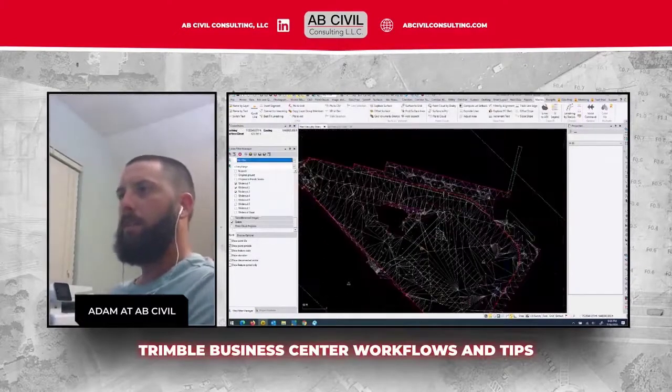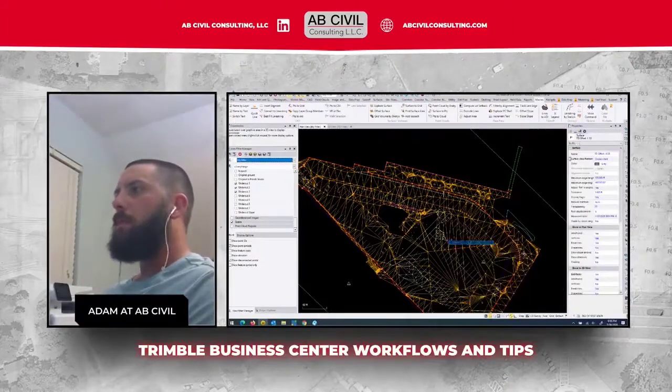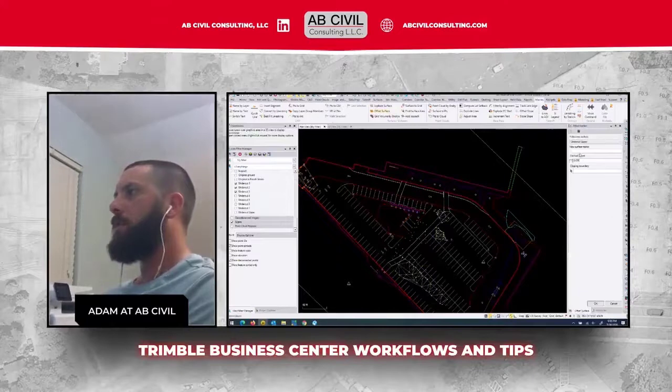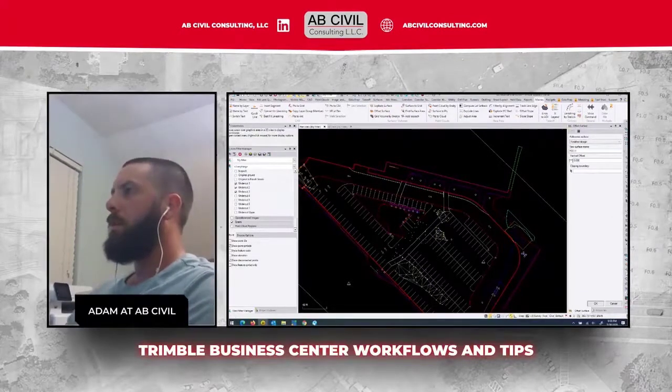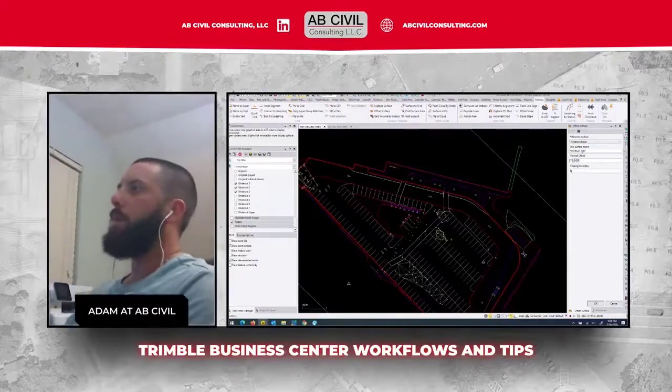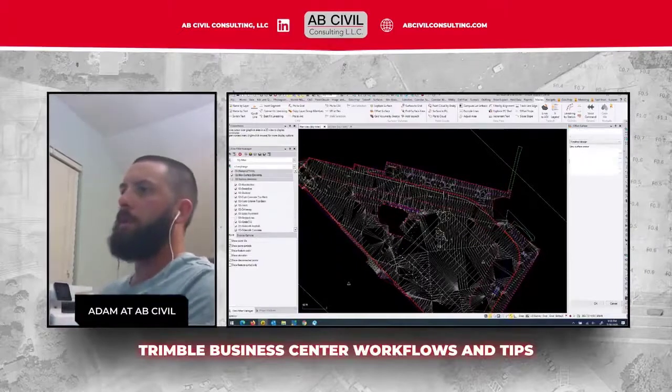It's not going to do it now that I offset the surface. Just do it one more time. Macros, offset surface, finished design, FD offset, minus 1.33, vertical minus 1.33. There we go.